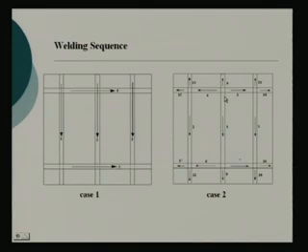So the middle stiffener, and literally I am starting from the middle, not from the end, but some point where it is crossing the transverse. Here the first difference is I am first putting all the stiffeners in place, means all the longitudinals are aligned, put in place, tack welded. Tack welding means small weld beads at intervals, just to hold it in position, and then put the 2 transverses, tack weld them. So the whole structure is in place.